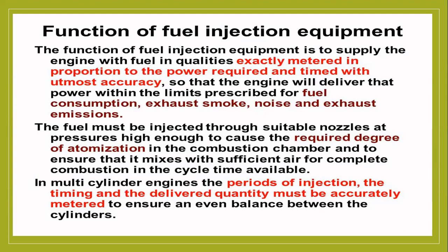In the suction stroke, only air is sucked inside the cylinder. Then the air will be compressed. After compression the air will heat up to 600 degrees C. So here we have 16 times compression. In petrol, I told you, it is an 8:1 compression ratio.